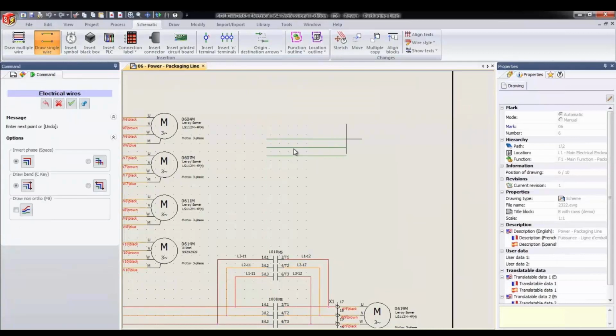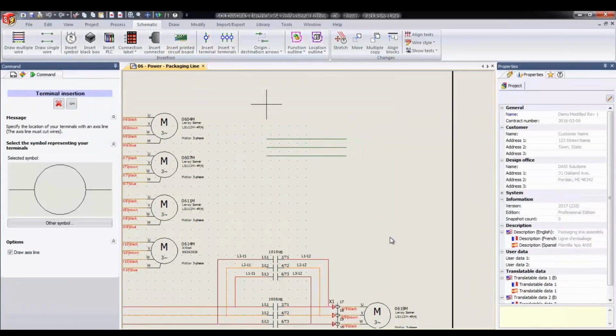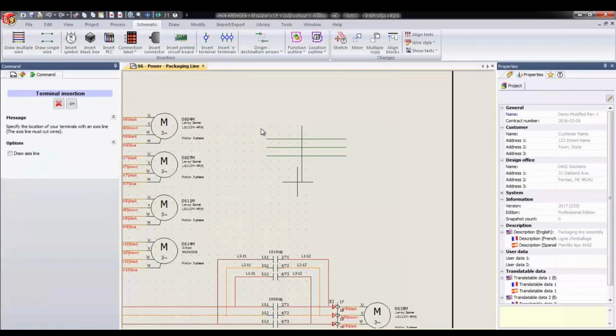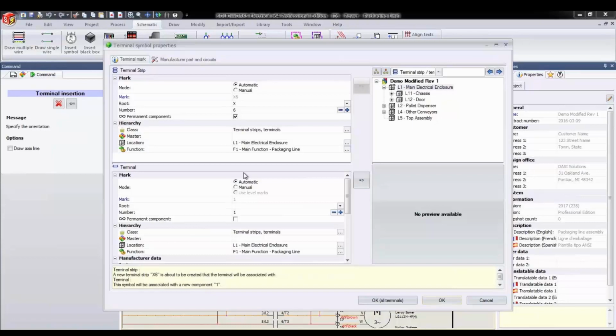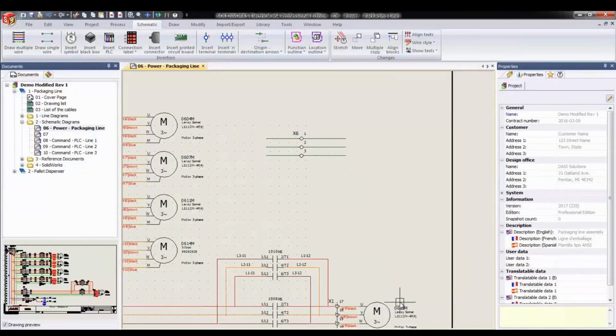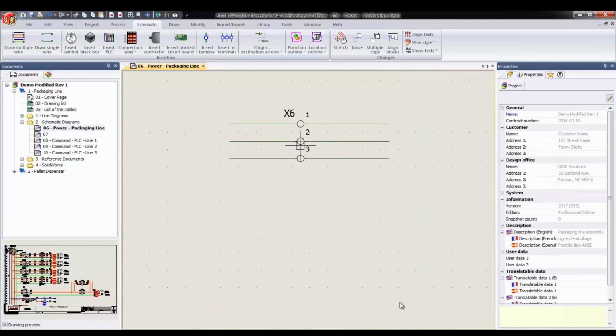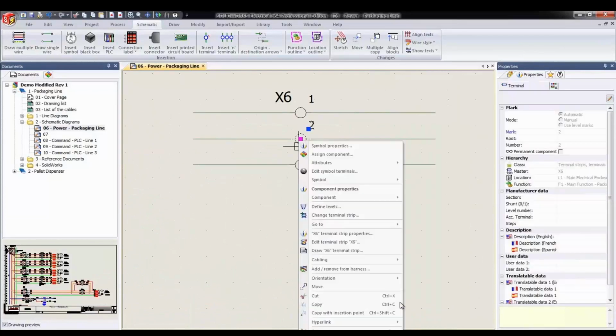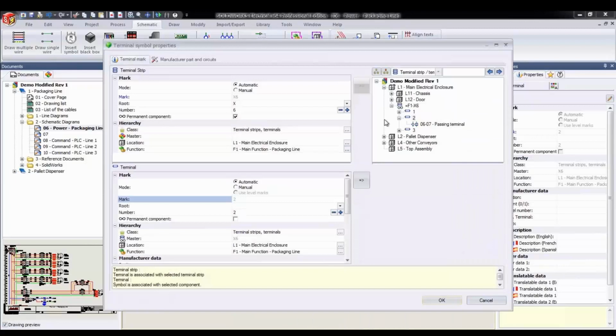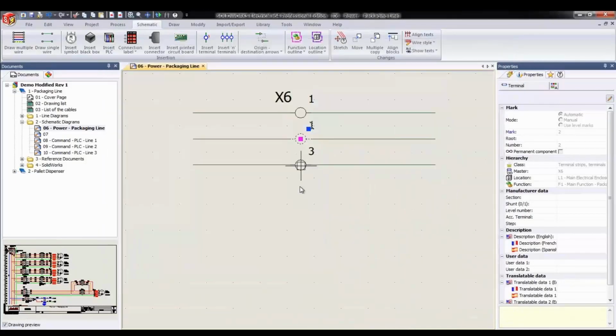Now those parts you can then go ahead and create. In this case here, we're going to just create some additional terminals because I want to show you how these terminals work. When you are utilizing the terminals, you can create your terminal strip. I'm going to do some terminal strips so that I'm using the multiple here. So I'm going to actually reassign the terminal to that first terminal so that I am actually making multiple levels.